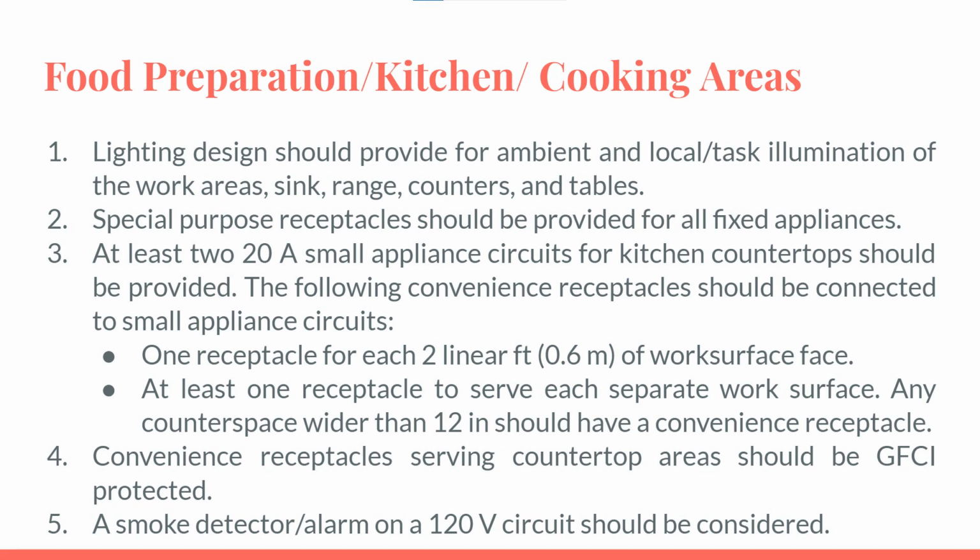Food preparation, kitchen, or cooking areas. First, lighting design should be provided for ambient and local or task illumination of the work areas, sink, range, counters, and tables. Lighting outlets should be switch controlled. Second, special purpose receptacles should be provided for all fixed appliances. Example, in range, built-in microwave, exhaust hood, dishwasher, trash disposal unit, waste disposal, and so on.